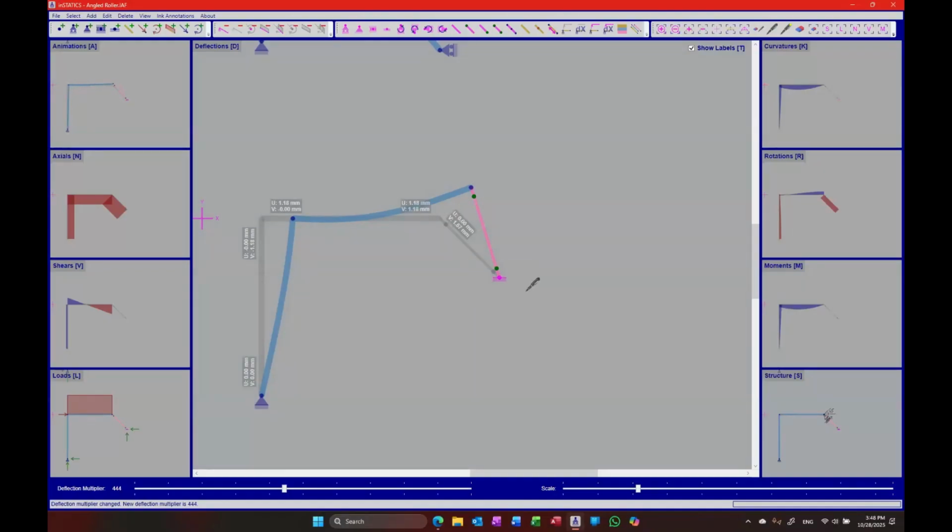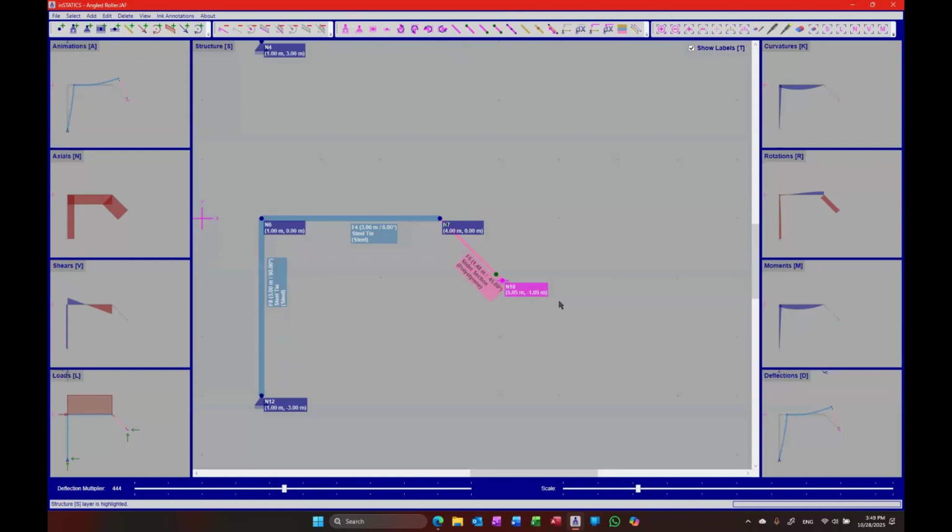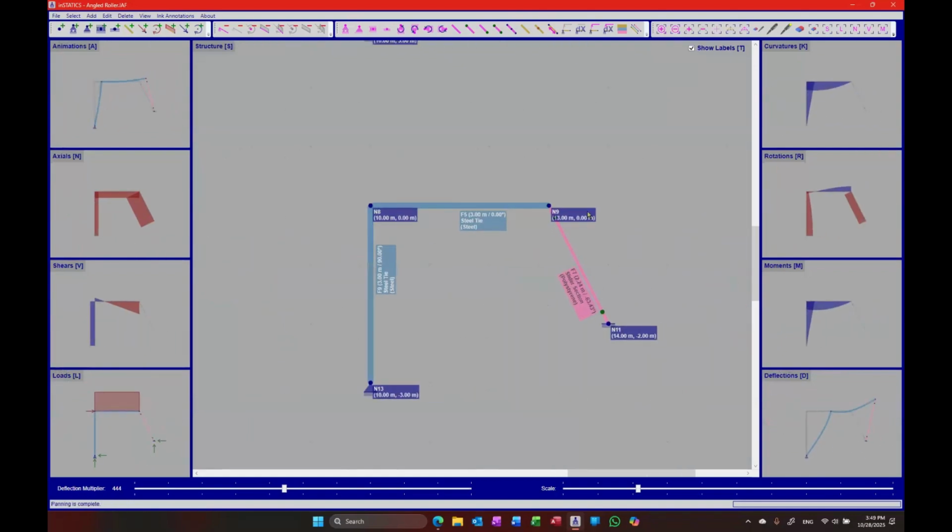Obviously, as long as this is 45 degrees, you can actually move this, right? And as long as it's 45 degrees, it will work exactly the same. Now, this also implies that if I want to, let's say, have a 30 degree roller, don't forget, right, this is, let's say, 63 degrees. So whatever's left from 63 is what I'm going to get here, right? Let me see if I can get it closer to 60. This one's closer. So it's kind of like 30 degrees in this direction. And you can make it happen by editing those nodes accordingly.